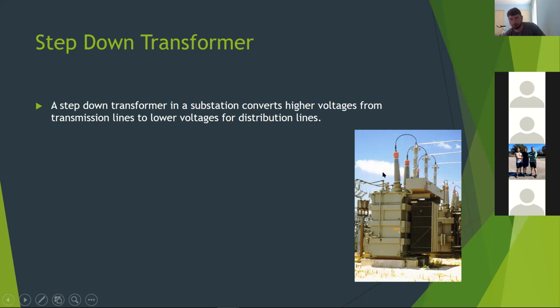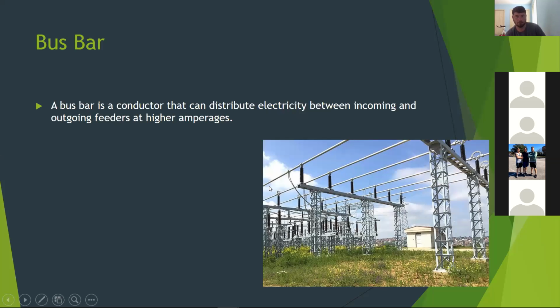Are we going right to left with the higher voltage? What size bushing do I have here? Left? Yeah, you got your smaller bushing on your left and your bigger bushing on your right. Which is distribution, should be your smaller bushing, right? And transmission on the left. Yep, on your bigger bushing there on the right. Correct, good. Yep. Said that backwards.